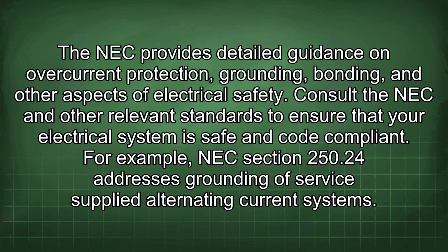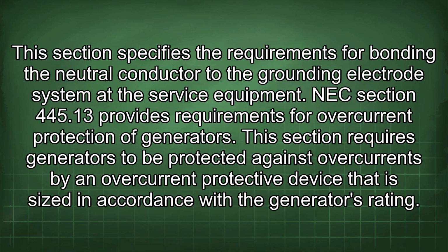For example, NEC Section 250.24 addresses grounding of service-supplied alternating current systems. This section specifies the requirements for bonding the neutral conductor to the grounding electrode system at the service equipment.